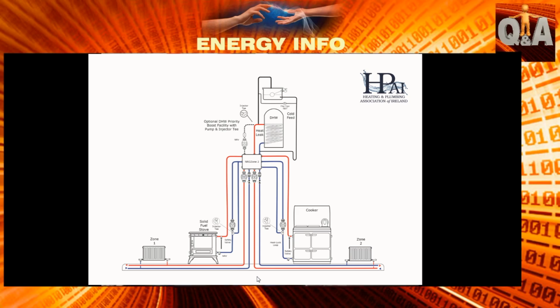So it's very important that the coil is able to handle the setback temperature from the two stoves when they're in turn down mode. Turn down mode means when the stoves are lighting and the cooker is lighting, but their dampers are closed completely. The coil should be able to take as much of that heat as is possible. But that is your heat leak, so basically the cylinder has to be able to take the two lots of heat leak from each stove.